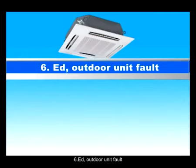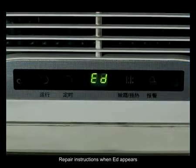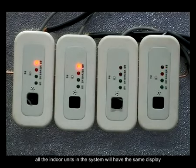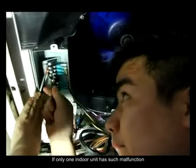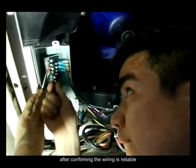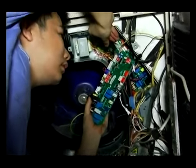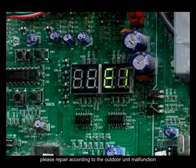6. ED, outdoor unit fault. Repair instructions when ED appears. When indoor units display that the outdoor unit has malfunction, all the indoor units in the system will have the same display. If one indoor unit has such malfunction, after confirming the wiring is reliable, you may change the indoor main board. If malfunction happens to all the indoor units in the same system, please repair according to the outdoor unit malfunction.